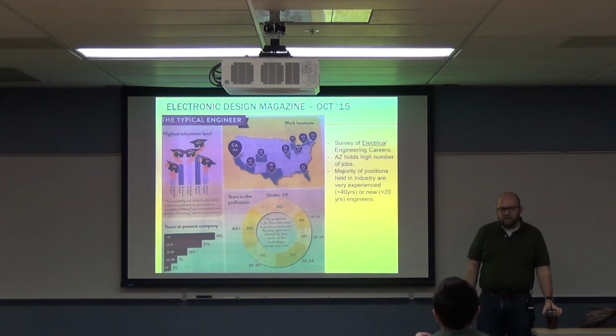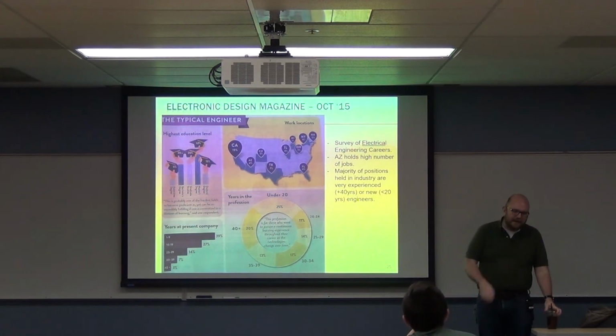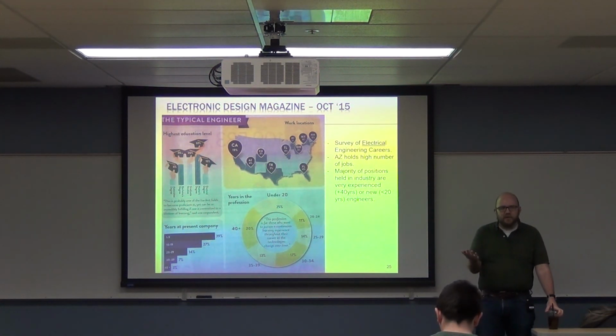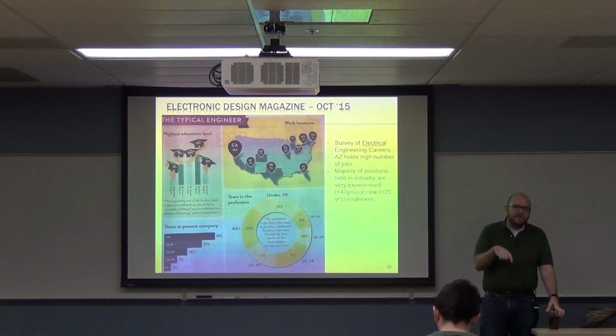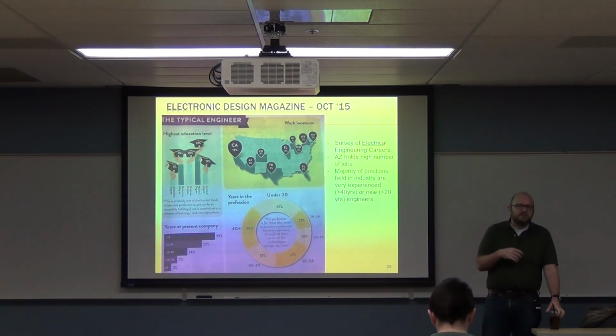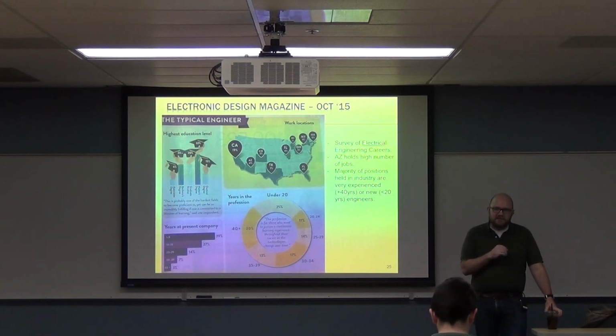So yeah, we have to run those decks, and those decks are complicated, and you have to write little scripts to parse the stuff that comes out. You have to automate it because there are like six checks I'd need to do. One of the checks is, did the thing I drew for lithography and manufacture match the circuit I asked for? And if I'm doing analog stuff, I might have implied certain passives to exist, like I might have drawn the metal in a funny way to imply a resistor. So I lied, you get resistors, but you want to make sure that resistor is there and it's the right length, so you have to write all the checks to do that.